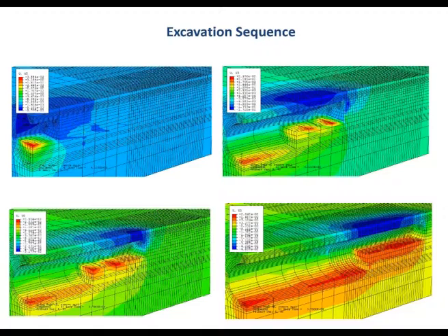Although you will obviously excavate the shotcrete, it is also 50 to 100 millimeter. So I think it's about 50 to 100 millimeter along this temporary. This is temporary shotcrete because every time you push forward, for this phase when you push forward, you excavate the shotcrete. For this bottom here, when you push the lower bench forward, you also excavate the shotcrete. So it's a temporary shotcrete. In fact, all shotcretes are temporary because you will come in later on to do your permanent lining.